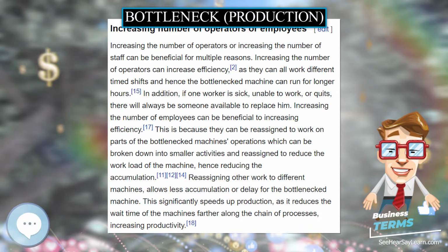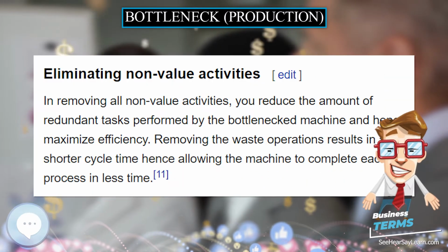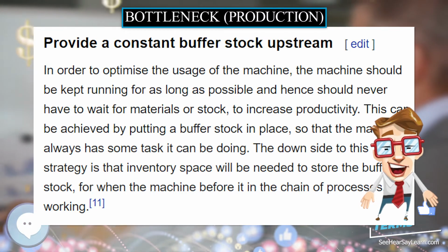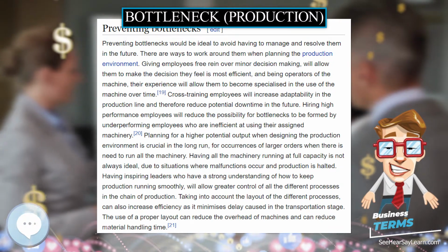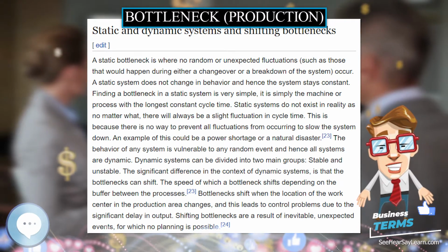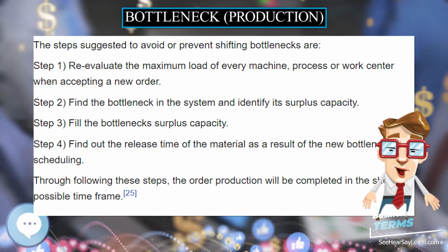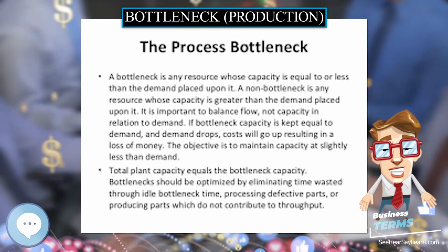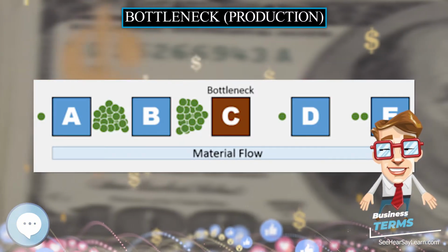Identifying bottlenecks. Almost every system has a bottleneck, even if it is a minor one. If every system was running at full capacity, at least one machine would be accumulating processes. Identifying bottlenecks is critical for improving efficiency in the production line because it allows you to determine the area where accumulation occurs. The machine or process that accumulates the longest queue is usually a bottleneck, however this isn't always the case. Bottlenecks can be found through identifying the areas where accumulation occurs, evaluating the throughput, assessing whether each machine is being used at full capacity, and finding the machine with the high wait time.